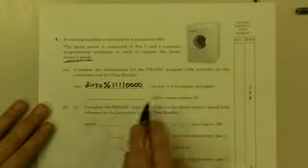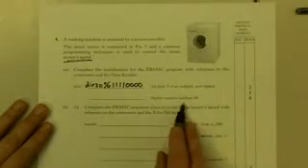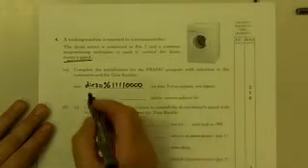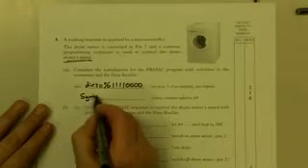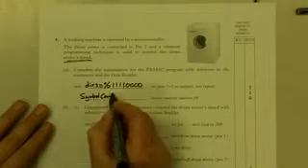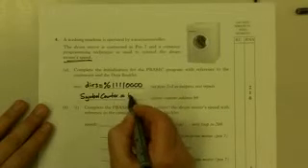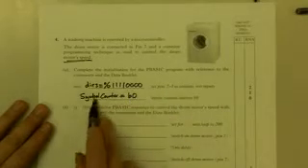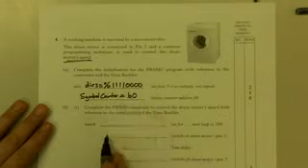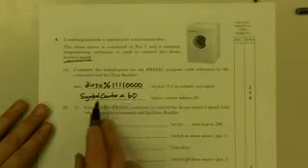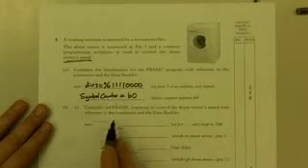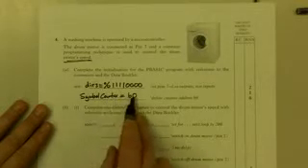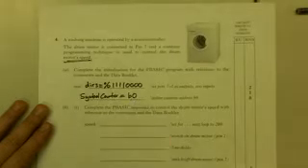So next line, define counter address as B0. Well, the command is symbol counter equals B0. Now you don't need to put this, you could just put B0 straight into the program for your for next loop, or you could define B0 as equaling the word counter. So you just substitute in the program the word counter for when you would normally put B0. Okay, on to the program.